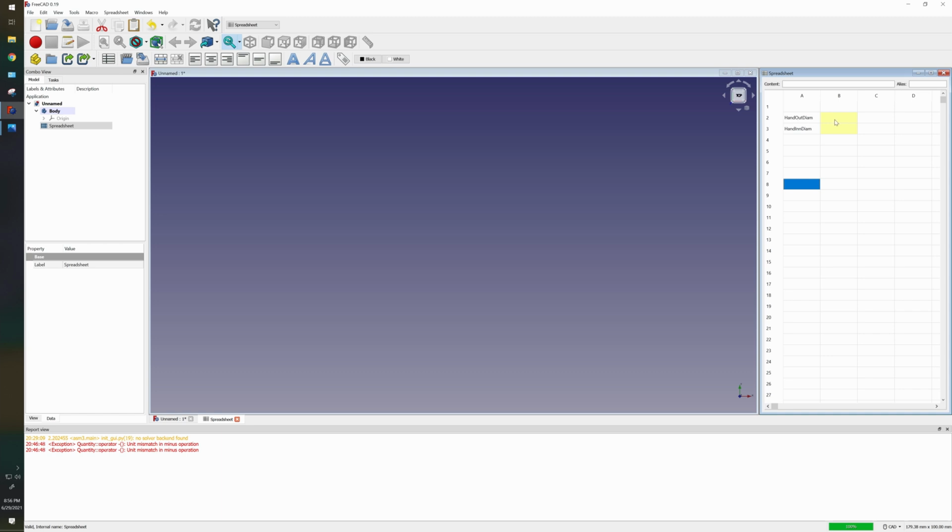So our outer diameter, I said at the beginning of the video, let's make it 4.8. Our inside diameter, I want to give it a value so that we don't get an error. So I'm just going to make up a number and say 3. We can always go back in there and change it. And you know what? We'll put ourselves a note here. Let's go exclamation mark. Just a shorthand to tell us, hey, change this later.